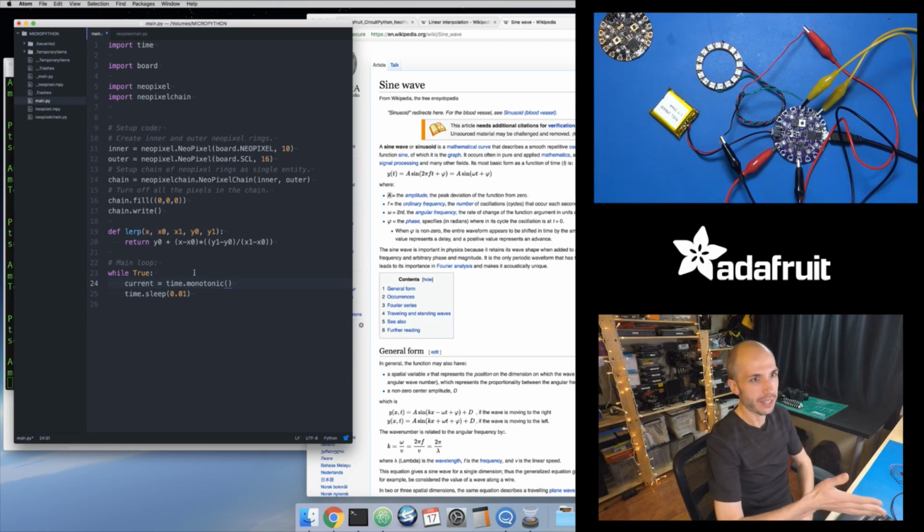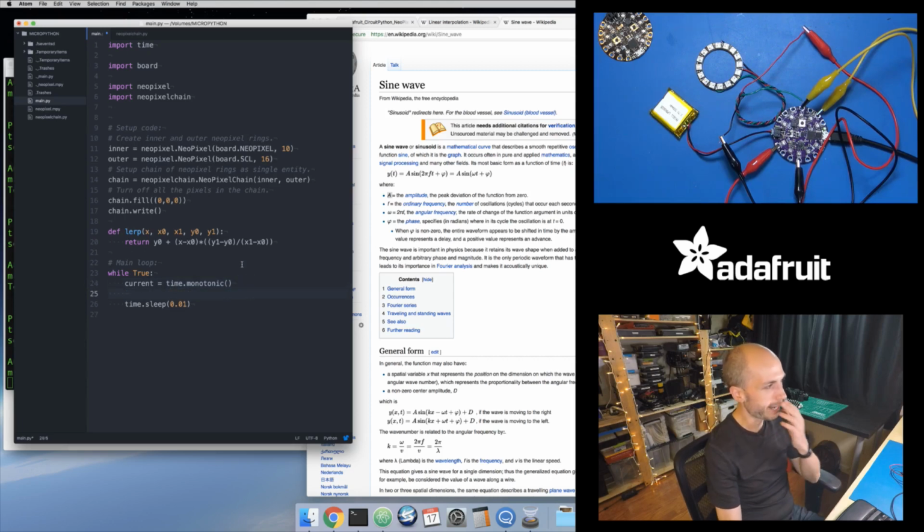I just care that it's X number of seconds, and that 2 seconds from now it's going to be X plus 2 seconds. This value is going to increase by 2. I just care that it's a value that increases over time, and that's exactly what the time.monotonic function does. In MicroPython, they don't have the monotonic function implemented. In the time module, you want to use ticks_ms, T-I-C-K-S underscore ms. You can get a millisecond tick count, which is effectively the same. But the nice thing is, in proper desktop Python, the time module has this monotonic function, so we figured, let's add that to CircuitPython so that it's the same as desktop Python. Okay, so that's my current time.